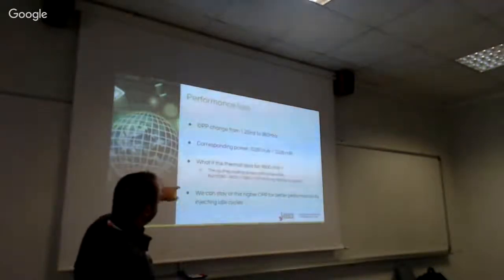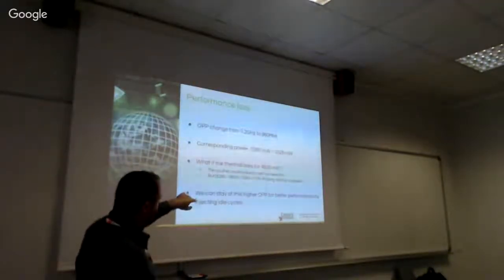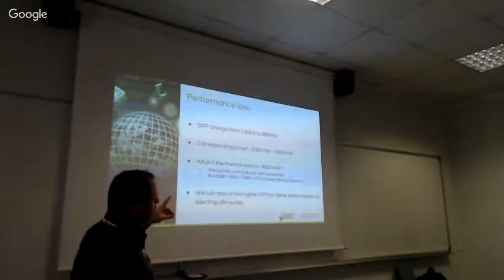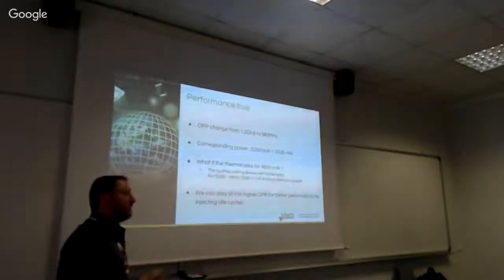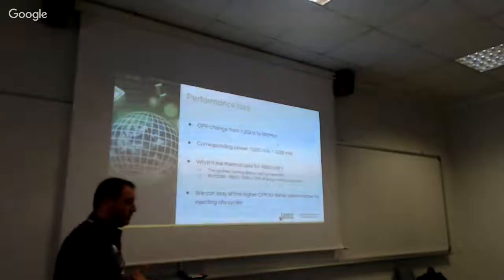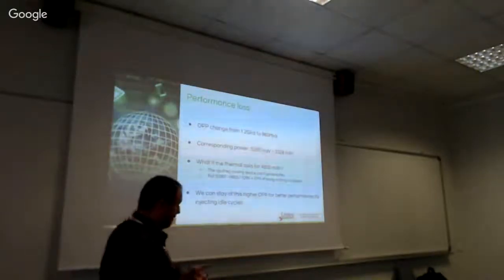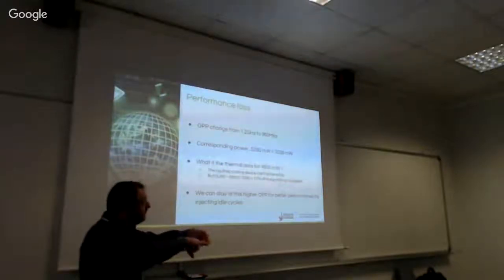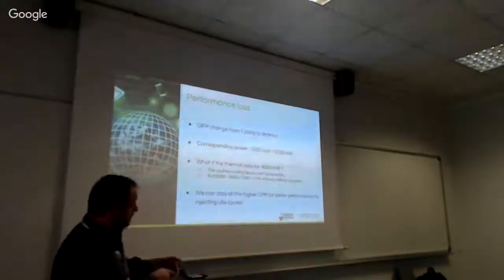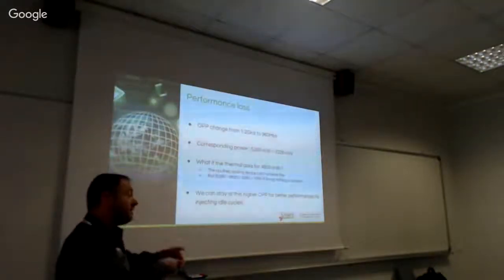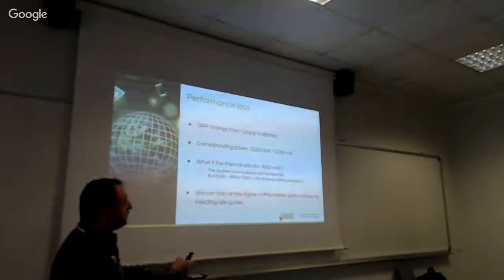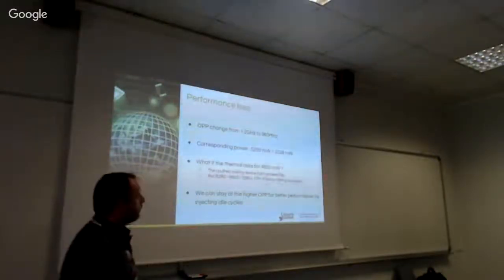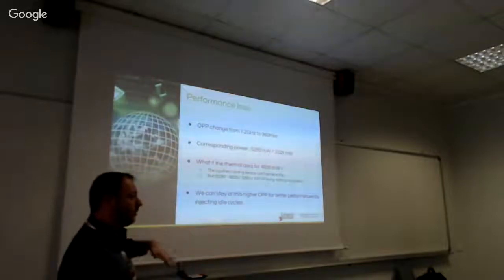So from there, if we are able to inject idle cycles and we are able to change the OPP, we are able to fill the gap between two OPPs and have better performance by injecting idle cycles before switching to the lower OPP.